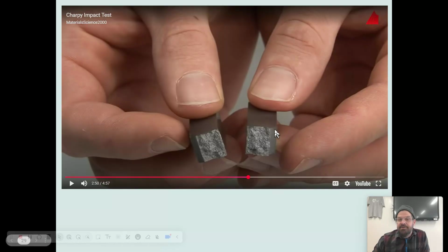So you can see right here, this was the part where the original notch was. All of this just meant that it was broken. It was brittle up along this edge here. So what you see here are just the grains of the metal, and the whole thing just snapped, right? So very little of it was actually deformed, and it was just pretty much snapped.